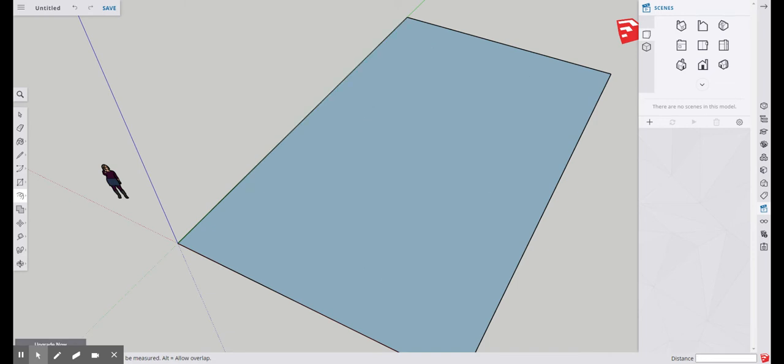Oh, no, sorry. I'm going to type 6 inches. A wall is not 6 feet. So redo. If I ever need to redo, this little back button will take you back, or you could hit Control Z on your keyboard. So back to what we're going to do. Make sure my little rectangle is inside. I'm going to type 6 inches, with the little double tick mark, click enter.